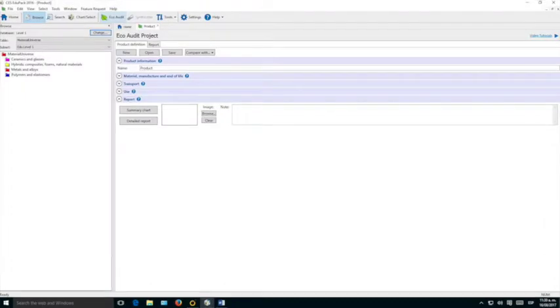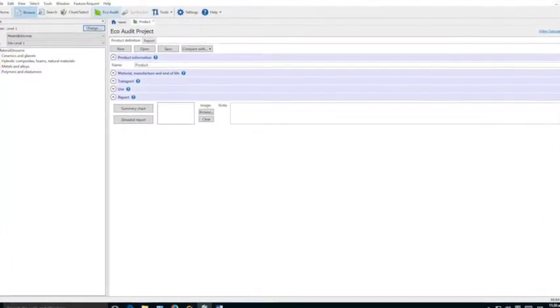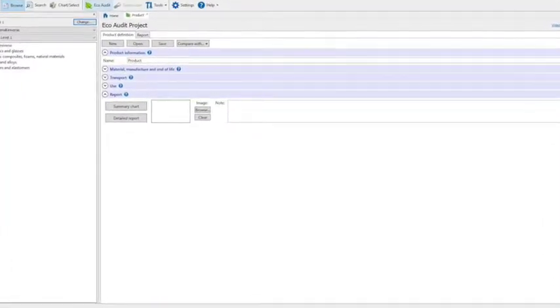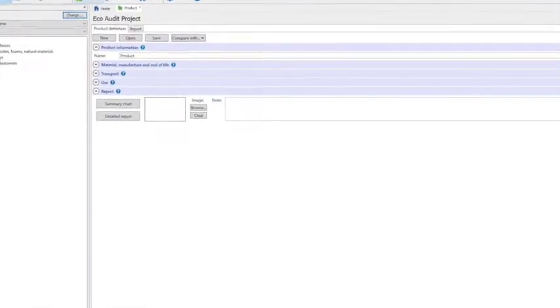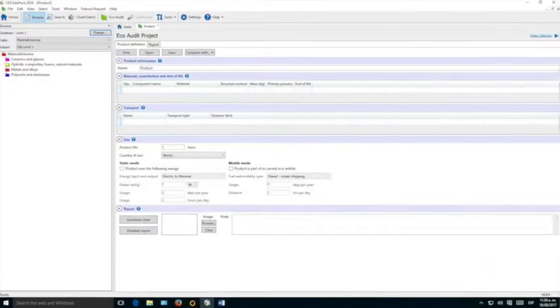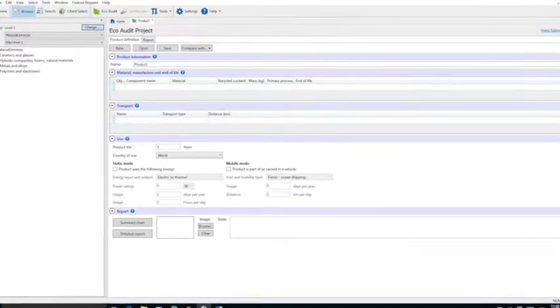An advantage that I see in this part of the tool is that we can compare different materials. For example, if we have a plastic bottle, after seeing the results, we can compare it with a glass bottle, so we can choose which one is better. The Eco Audit tool is located in every window we select. It is located in the top part of the window. When we click it, it opens a new window called Part 1.